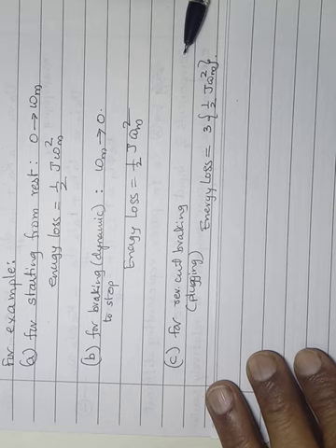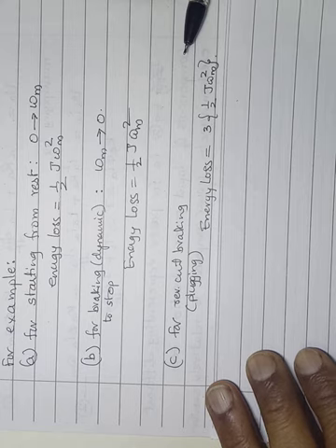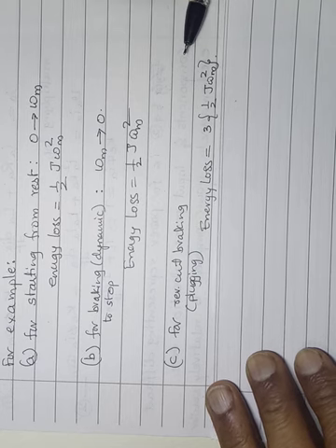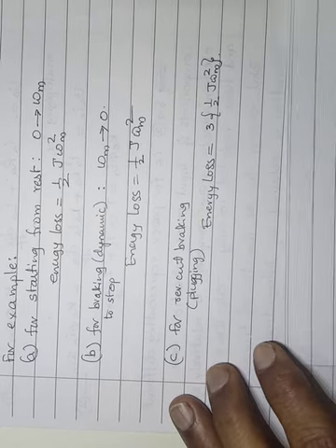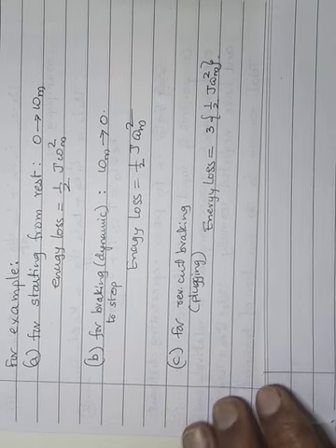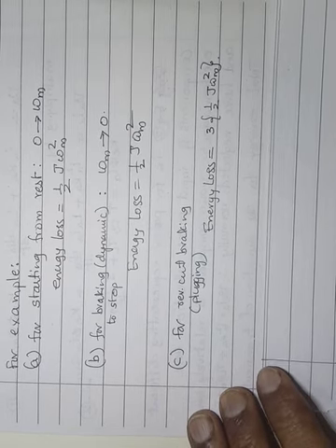Of course, we also mentioned the merit of plugging, as it is the fastest method of braking. So in plugging, reverse current braking, the energy loss is maximum, but it is the fastest. The higher the deceleration, the quicker the braking, at the cost of higher loss. Is it okay? So that's how we can calculate the amount of energy lost during the transient operation.